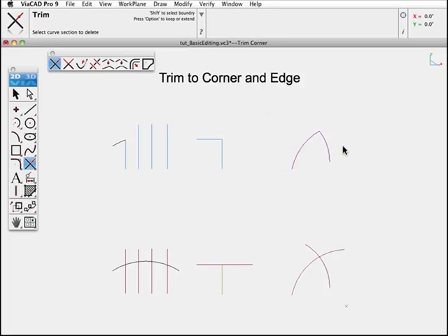By pressing the Shift key, you can extend the boundary edge that we're trimming to. And now I'll click the arc and it deletes away the portion of that intersecting arc to where it trims. In this case, we've extended to the arc. Just click the items you wish to trim to that edge. From our View menu, let's pull up the user view called Break Trim.